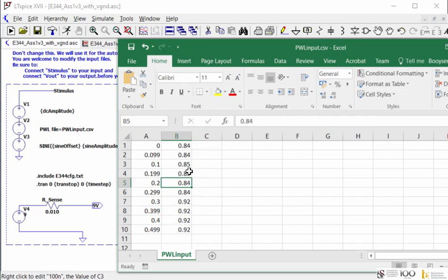The reason I've done this is I wanted to check and confirm the step response, so the time that it takes for the output to reach 90% of the full output for a 1 degree step. And then I've stepped it back just for good measure, and then made a massive leap just to see what it looks like.